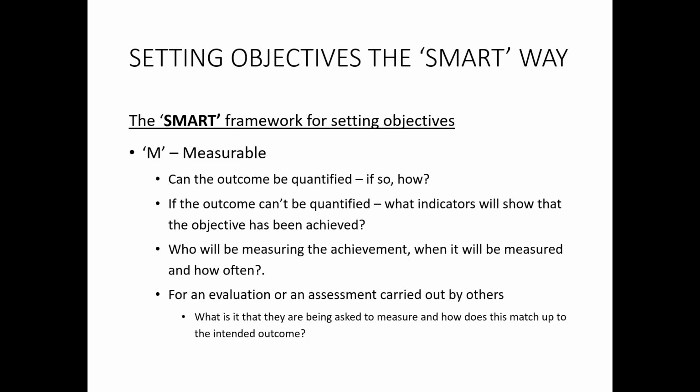All those things, if we are specifying, then that is measurable. Example, we are designing a portable drilling machine under 2 kg, maximum weight should be 2 kg. So there is a measurable aspect. So always we should frame the objectives such that it is measurable. And if it cannot be measured, then there should be other indicators that will tell you whether the objective has been satisfied or not.